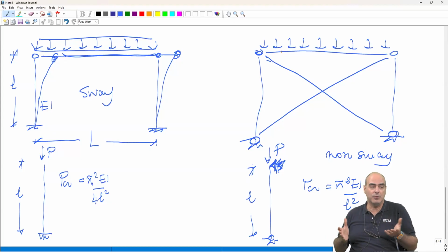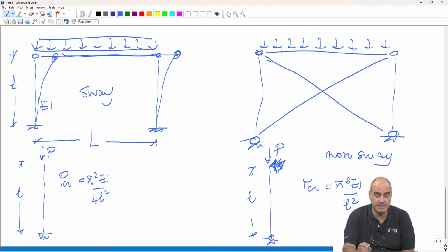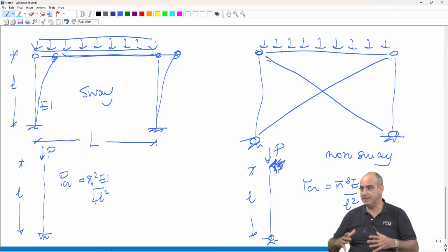because one issue could be, okay, you say, I have to, for example, jacket my columns. I increase their cross-section, I increase the stiffness, and I can get it. But, you know, that requires a lot of work. One possibility will simply be, well, we said before, we accepted to go from fixed edge to non-fixed. Why don't we act on the foundation elements and try, for example, to encase them?